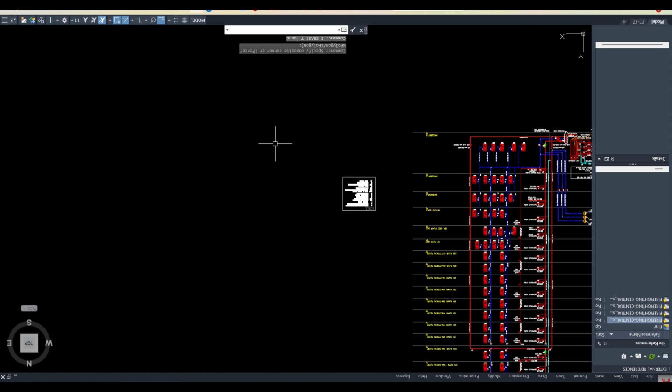Okay, let's say I have a building where the height from the lowest grade till the parapet level is 90 meters. In which category will that building come? From the lowest grade till the parapet, 90 meters, which category? Still high rise. High rise building. Why not super high rise? Because the height of the parapet is excluded, we cannot include that one.